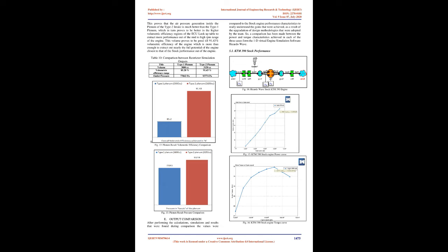Boundary conditions common to both types of intake: the inlet pressure of both types of intake was the same, equal to 101,325 Pa, or 1 bar, as normal atmospheric pressure. Temperature for simulation equals 35 °C, considering the event's atmospheric temperature. Throat pressure of the Type 1 restrictor equals 56,742 Pa.